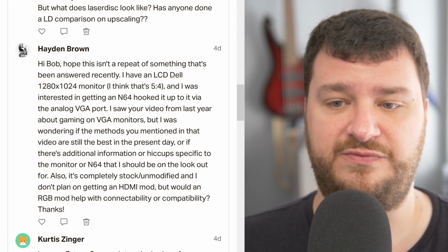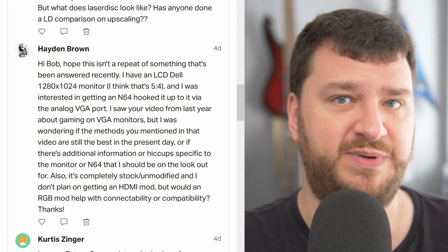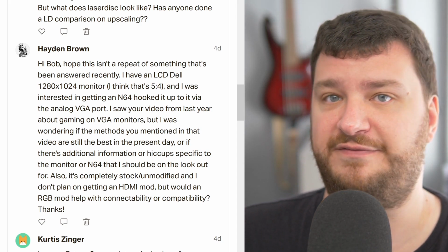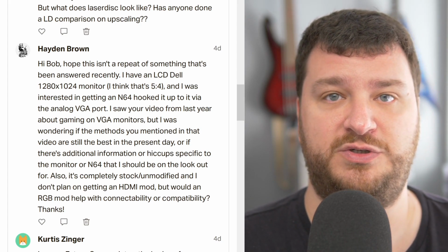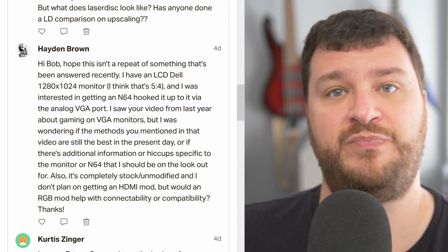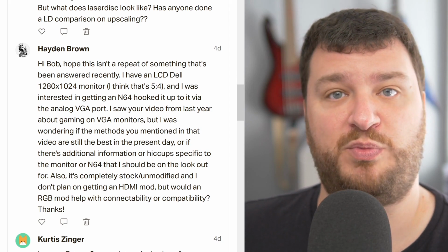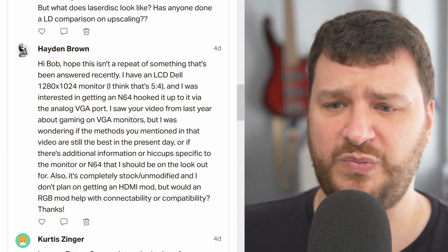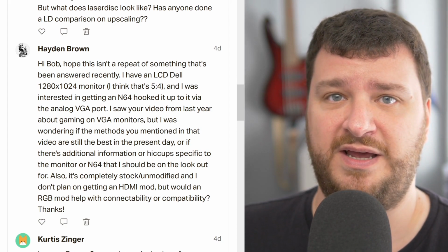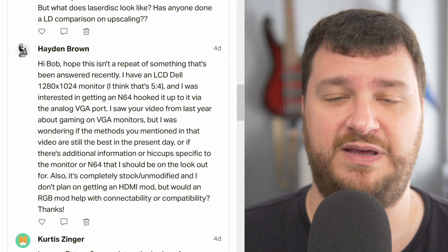First, that video was very specifically about RGB signals on CRT VGA monitors. So the purpose is basically to line double a 240p signal to 480p, add scan lines, and then turn up the brightness on your VGA monitor, assuming it's still in good enough condition to do so. And you'll end up with a CRT that looks pretty much like a PVM.